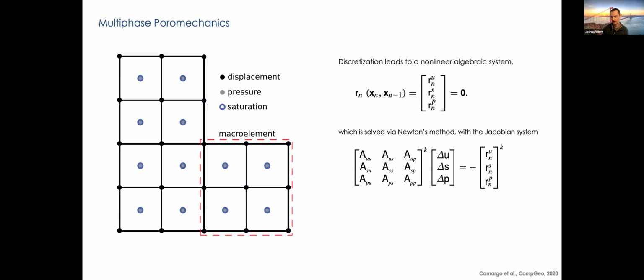Okay, so those are the typical governing equations. In terms of a discretization, I can think of at least 10 good ways to discretize this system of equations. It's a very active area of research. What are good discretization strategies? I'll show you one, which is a pretty typical one, and probably the most commonly used in practice, but there are certainly others. The key thing is that because these processes are relatively slow in time, we tend to use implicit time integration. Okay, so we're going to come up with a system of algebraic nonlinear residual equations.